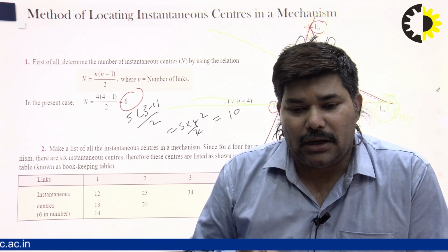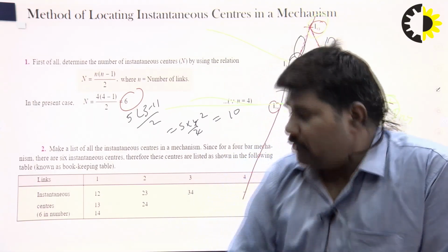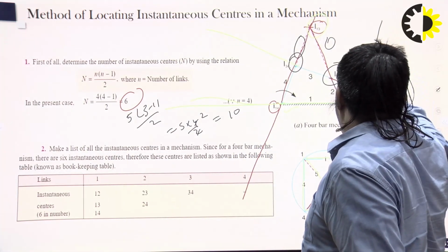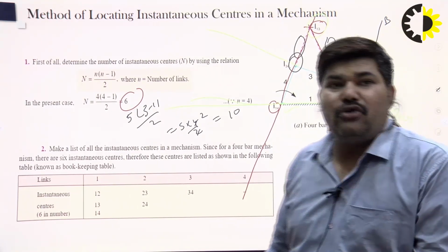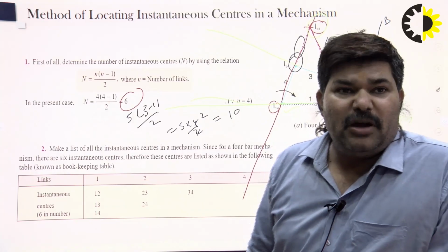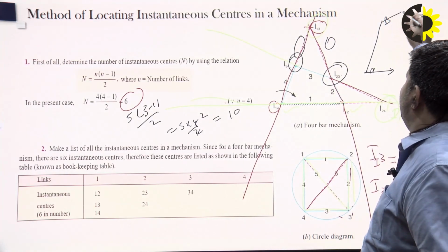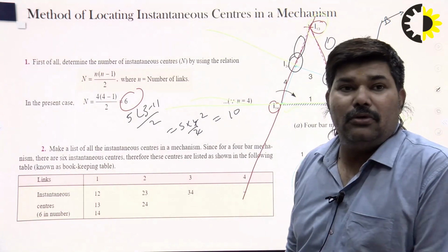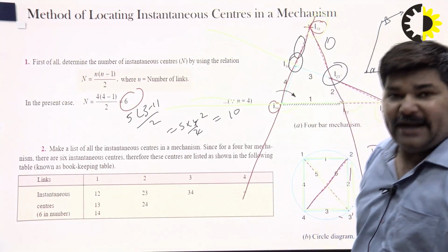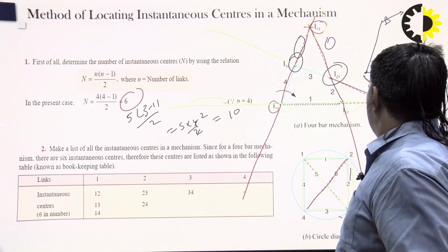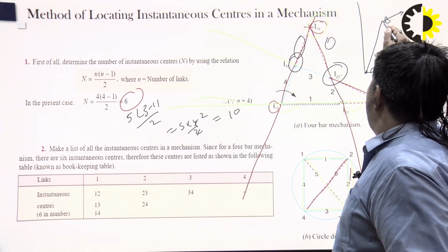Mostly, suppose you draw the velocity, you can see the link AB, right? For link AB, at point A the magnitude and direction are given, but at point B only the direction is given. So what we do is find out the magnitude at point B. In that case you draw the velocity perpendiculars to this and to this.